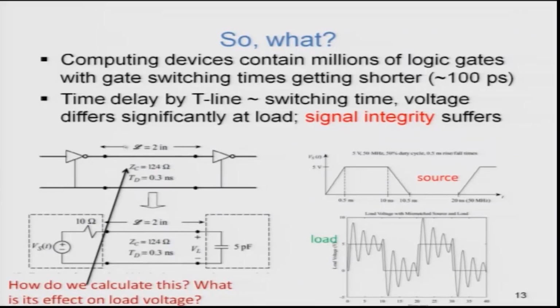It also turns out that the wire does more than just give you delay, it also has an inductive and a capacitive type of behavior. So, we need to understand completely the model of a wire to better represent this situation and to avoid this kind of behavior. You can actually see that if I somehow do not manage or match this load and the source, then my voltage waveforms do not come out as expected, but they will have a lot of non-idealities or distortions.